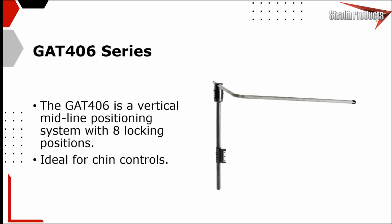The second is that chin control on the Gatlin in this way attaches to the chair, right? Either to the center spine or an upright cane, things like that. So if that chair has power recline, what that's going to mean is that accessing the joystick becomes more and more difficult as the client reclines backwards. The joystick will have a tendency to migrate upwards in relation to that user's chin with the more recline you introduce.